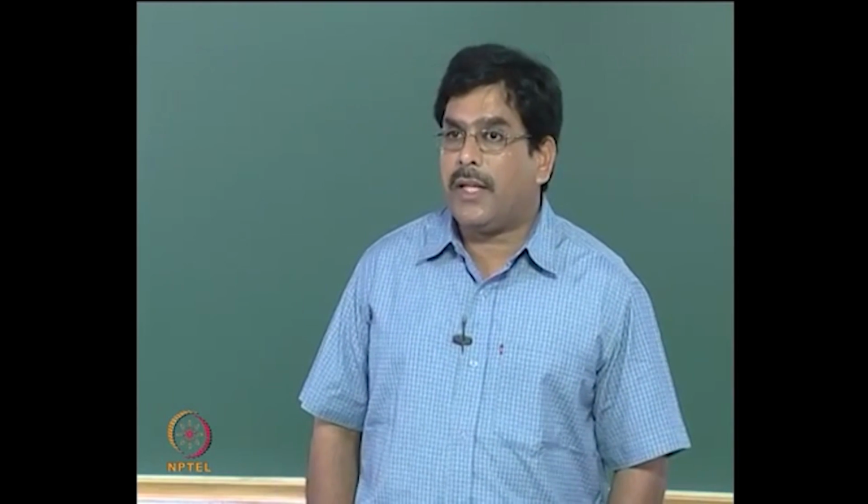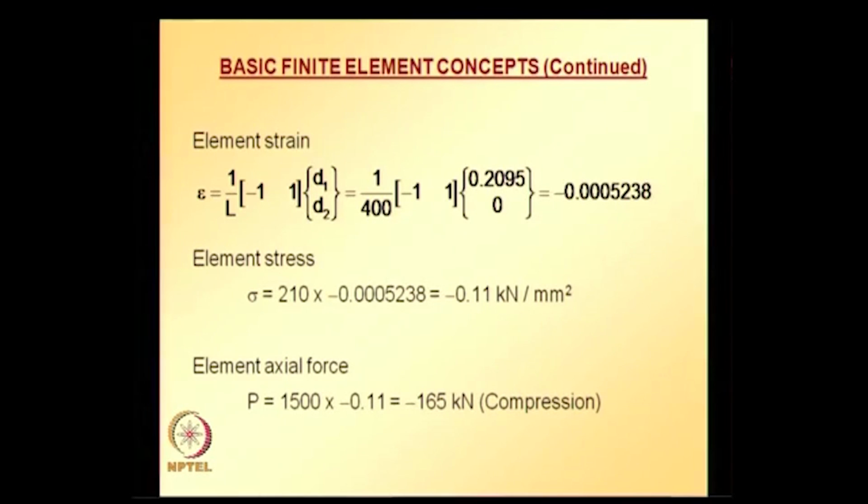Now let us first derive the equation system for a 3D truss problem, a 3D space truss, whereas a 2D truss is a plane truss. A 3-dimensional space truss element can be developed using coordinate transformation and the local elemental equation for axial deformation element, in the manner in which we did for the 2D plane truss element.